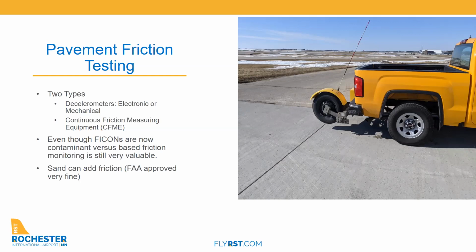Many of you may still use sand. We do a little bit. The FAA approved sand is more like flour, in my mind. Very fine, hard to keep on the pavement. And for those that are familiar with the new RCAM system, it really doesn't give you a lot of benefit. There's not a lot of upside to sand other than, in the real world, it helps the friction, but it doesn't really help you on your RCAM and your field condition much at all anymore. So we don't use as much sand. We use more chemical than sand, but it doesn't mean that it's still not a valuable tool for the rest of you out there. Next, please.